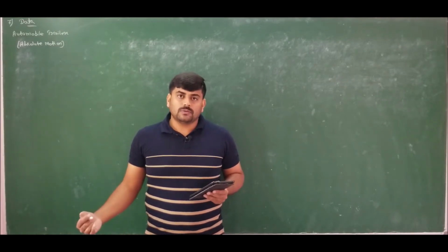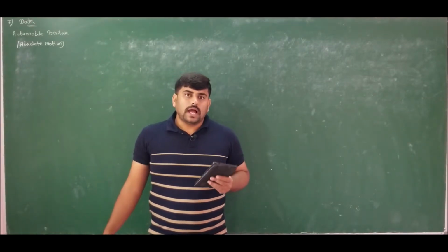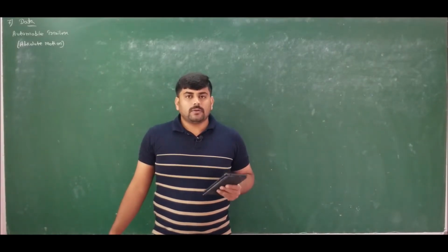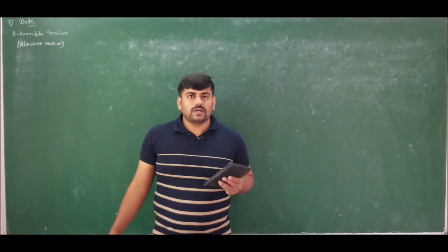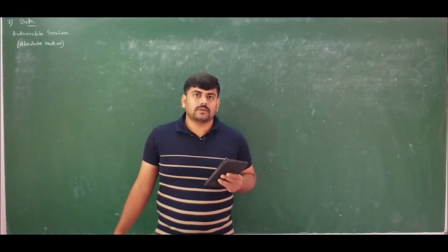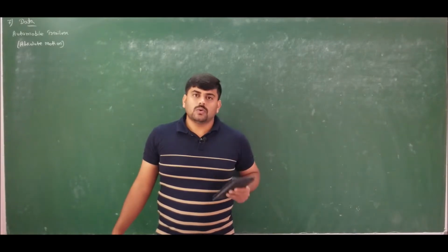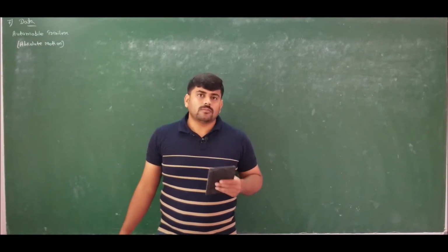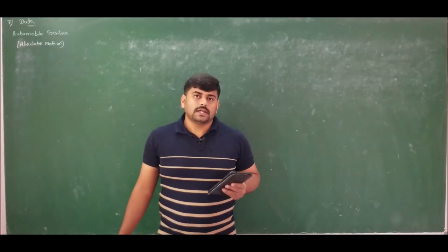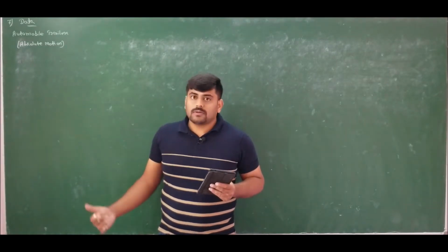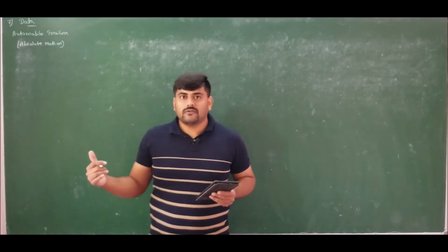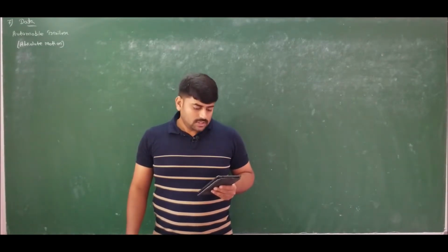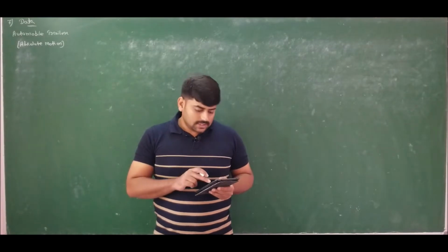Now for absolute motion we have derived the expression for amplitude ratio, that is A by B is equal to square root of 1 plus (2 zeta omega by omega n) whole square, divided by square root of (1 minus (omega by omega n) whole square) whole square plus (2 zeta omega by omega n) whole square. Hope you remember that, because we have already recollected the formulas we derived so far in our first lecture of problems, when I solved problem number 1 of our discussion on forced vibration. Hope you remember all the formulas. Let us move ahead.